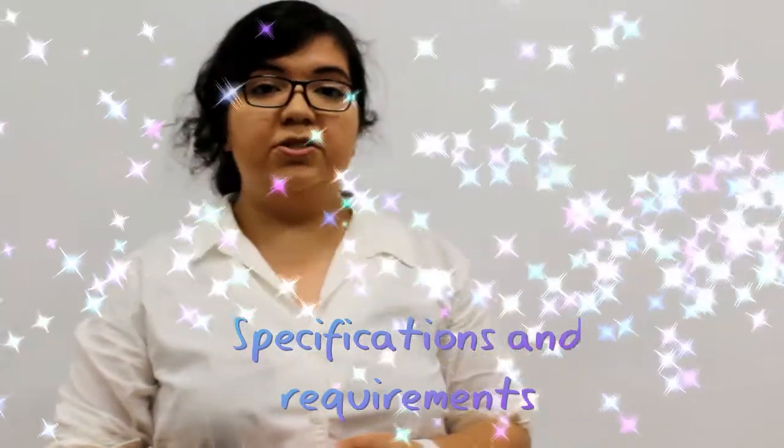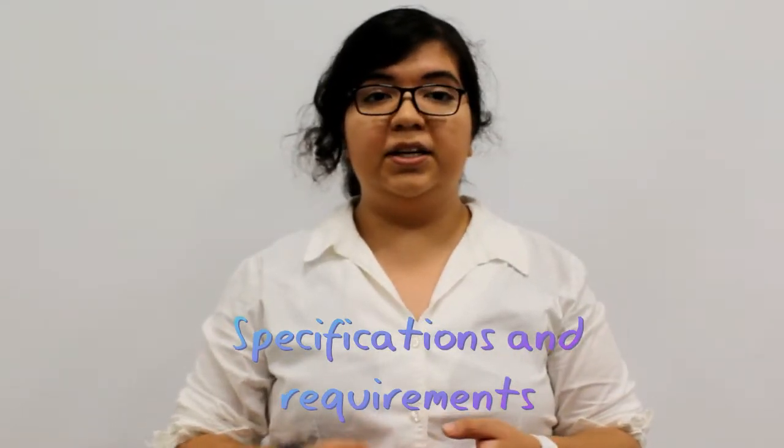We will use stepper motors in order to make the movements of the frosting in X and Y axis. We will work in a 2D plane. How will we perform these movements? According to the design desired by the client, we will use Arduino interface, that is basically a C++ language. And also we will need the software or extension GRBL that serves as an interpreter for the G-code in the Arduino. So we implement this and it will interpret the movements in X and Y according to the desired design.